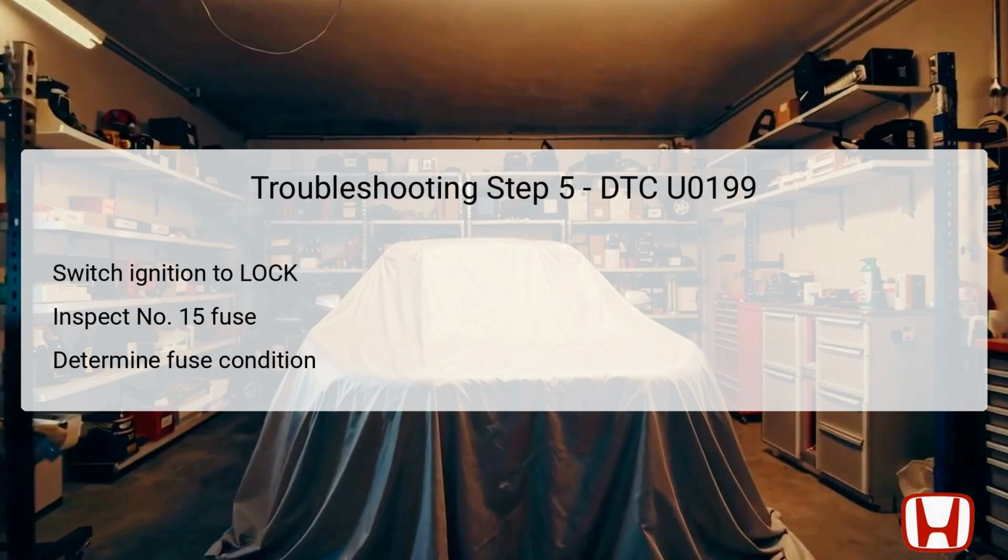If the fuse is still intact, then the next action involves repairing any open circuit or high resistance within the number 15 fuse circuit itself. Conversely, if the fuse is found to be blown, it will need to be replaced. Persistently blown fuses indicate potential short circuits that also require repair for a successful resolution.